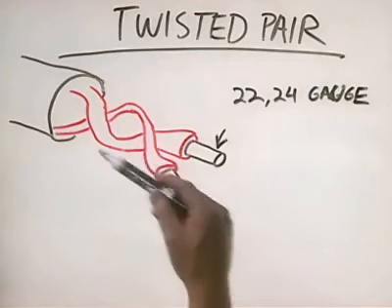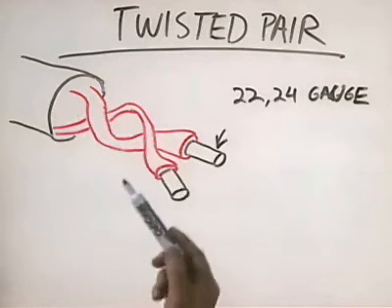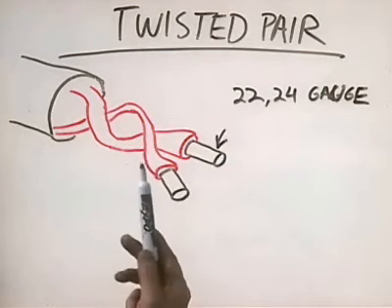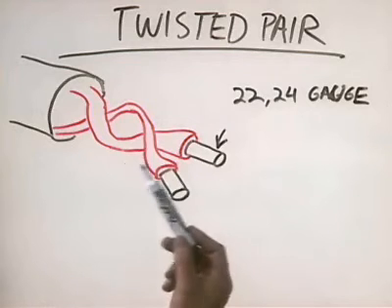It's a radio signal that's being broadcast from the wire. It's not intended, it just happens. Well, the problem with twisted pair wiring is that this interference can be absorbed by the neighboring wire, which interferes or disrupts its signal. To get around that, we twist the wires together. That way, the electromagnetic fields that each wire is emitting cancel each other out, and we negate the problem of EMI. As you can see here, we have the wires twisted together. The tighter we twist these together, the less electromagnetic interference we experience, and hence, the faster we can transfer data through these wires.